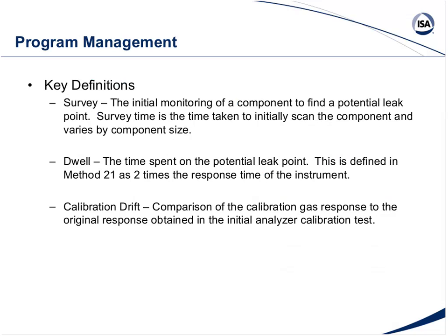We have several different time periods that we deal with. We deal with the time periods from scheduling and looking at our leaks, but when we're actually doing Method 21, we do a survey to see if I'm seeing a leak. So that's the first piece of time that you'll have when you're doing your Method 21: that survey. Did I see a deflection that's going to cause me to have to stop and look at this component and look at this particular spot in this component a little longer? Then I have to make sure I'm staying the appropriate dwell time.